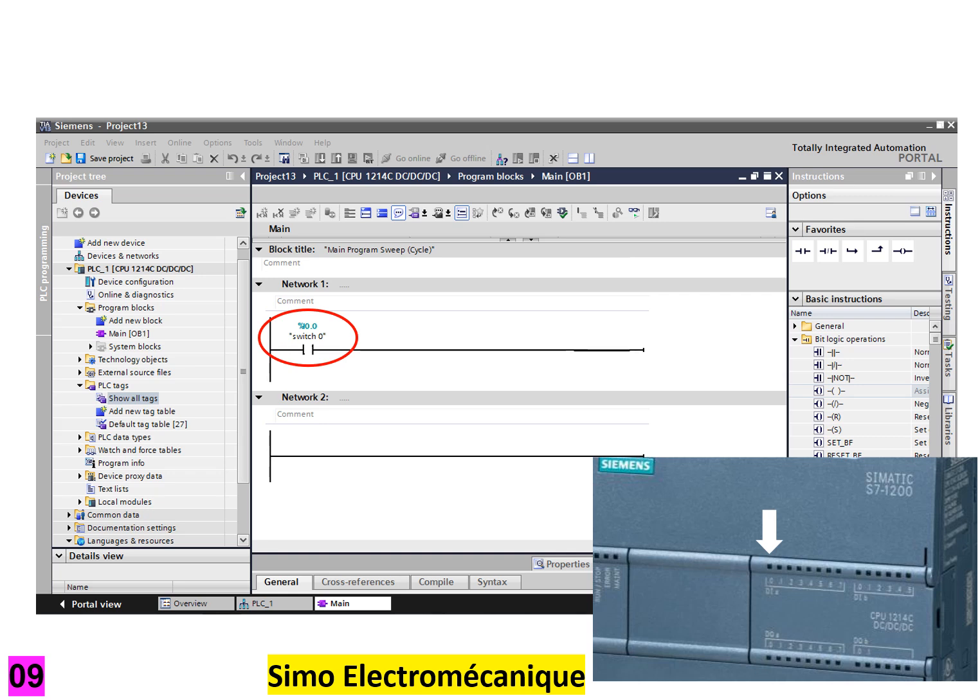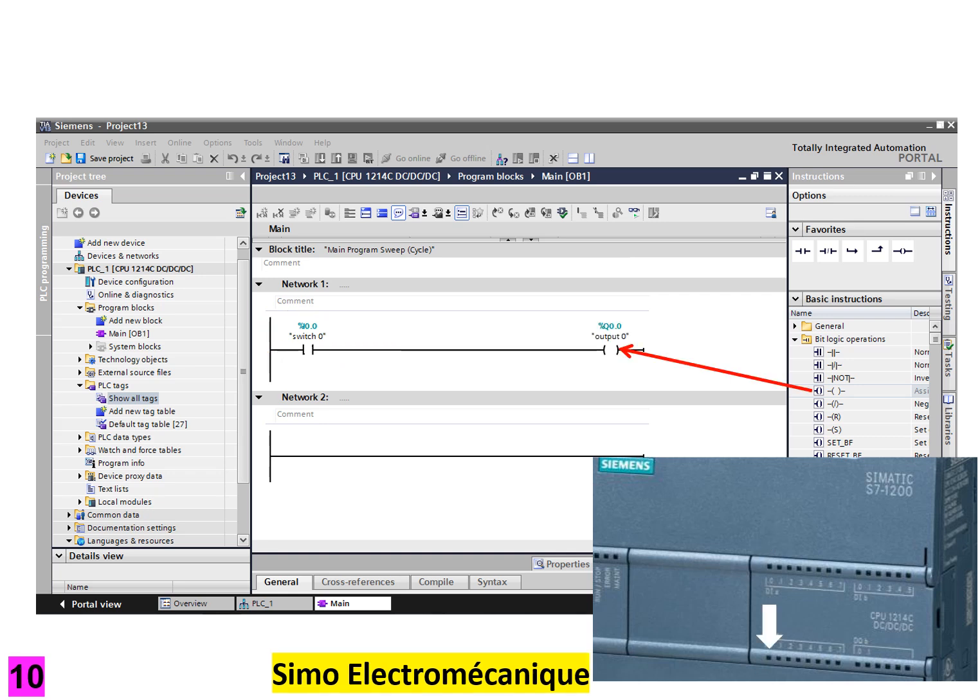I0.1 would be the second, I0.2 would be the third, and so on. We can then click and drag a normally open output to the right-hand side of the ladder, as shown. Click on the red question marks and enter Q0.0. This means we want the first digital output to be driven by this circuit.